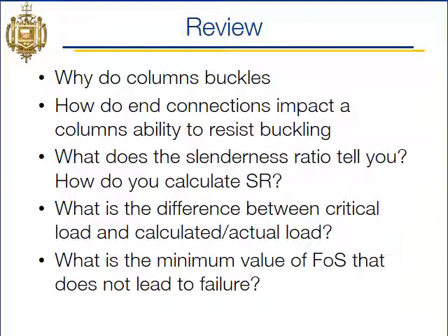The slenderness ratio allows you to classify your column between short, intermediate, and long and slender, right? And remember, we always want to pick the higher slenderness ratio, so we need to analyze both the slenderness ratio for the x and y axis, and that calculation is KL over r. The difference between critical load and calculated load. So critical load is what load will cause the column to buckle, and the calculated or actual load is what we're actually going to put on there.